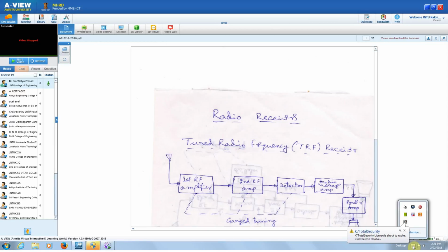RF amplifiers, because the input signal that we have is, as I said, 800 kHz, a radio frequency signal. Therefore we have the required RF amplification input stage, with two or three stages of amplifiers depending on the required level of amplification. That is given to a detector to detect the baseband signal.